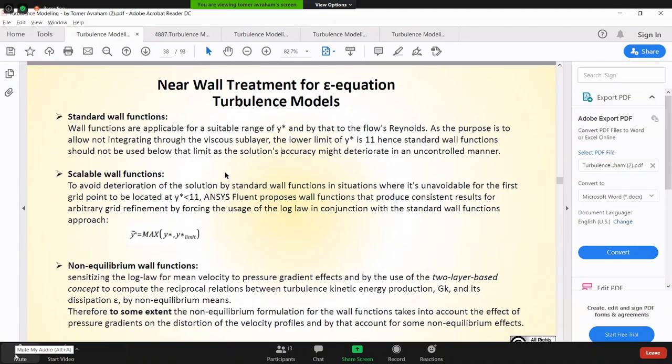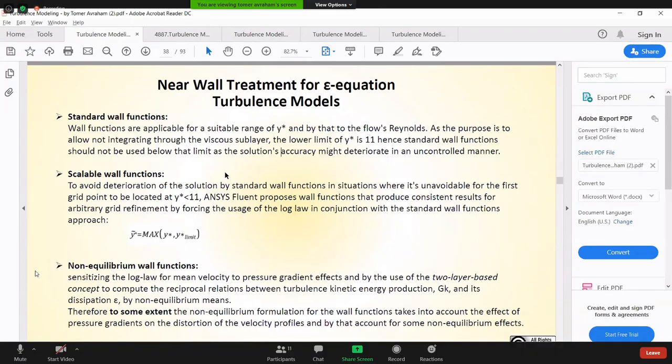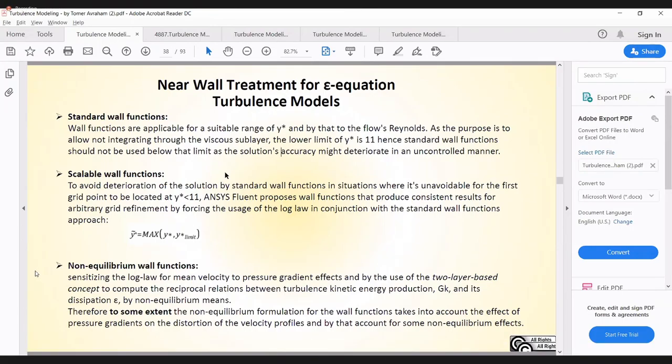If you've done something wrong in these parts, either you checked your eddy viscosity ratio and it's well outside the boundary layer, or from the other side, you did a validation but the results are horrible. And so there is not a preferred model.